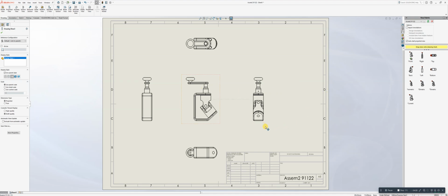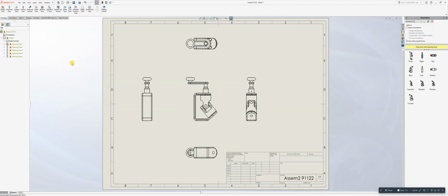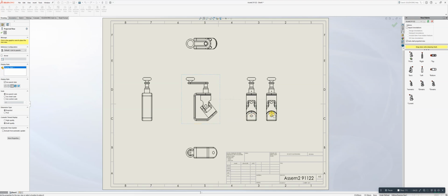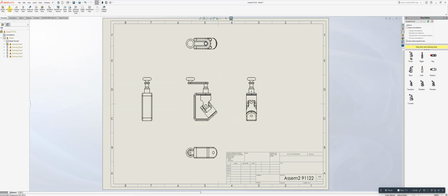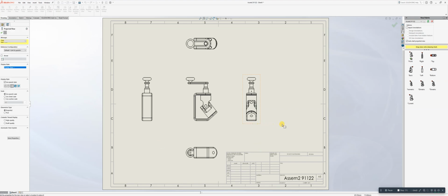So I've got general arrangement there. If you wanted to add in a third view, you can do. To do that, I just go to escape. I know I've got problems here, but that's purely because I've cobbled together this picture just to try and demonstrate to you. If I want to do another view on that side, I just go to projective view. If I click on that one there, and you can see the view comes out again, or if I go projective view again and click on that one, I should get that view there. It just works it out automatically on that. So I've got various views there. I might as well use the majority of them.